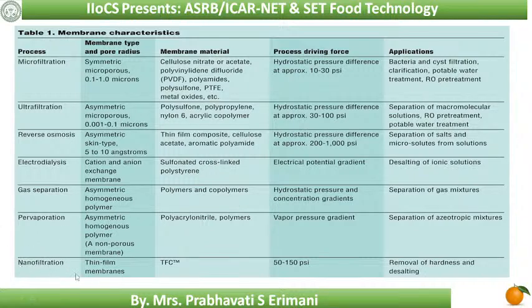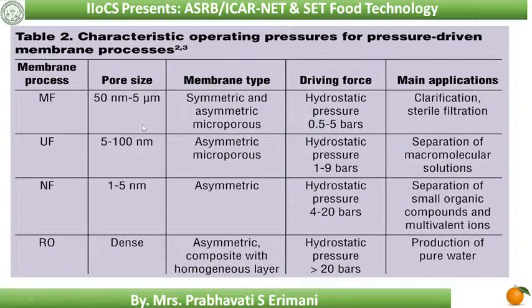In case of nanofiltration also, a thin film membrane is used, that is TFC, which is the material name, operating at 50 to 150 psi, for removal of hardness and desalting. Okay, so these are the things. Here also some of the same things, a little bit of some extra things will be there.